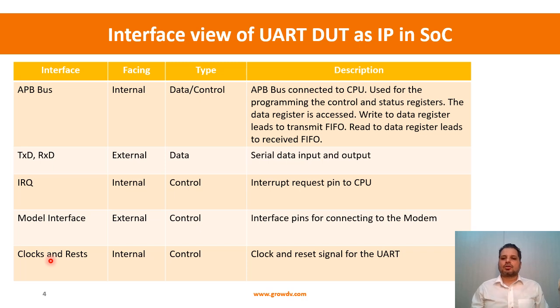So this gives us the overall idea of what the interface signals are and how we need to configure it. Our primary focus will be on this APB bus, so that we can access both the data and control, and TXD and RXD so that we are able to transmit, and a bit of IRQ, right? And clocks and resets, of course, is not much. We will not be worrying too much about the modem interface as a part of this session.